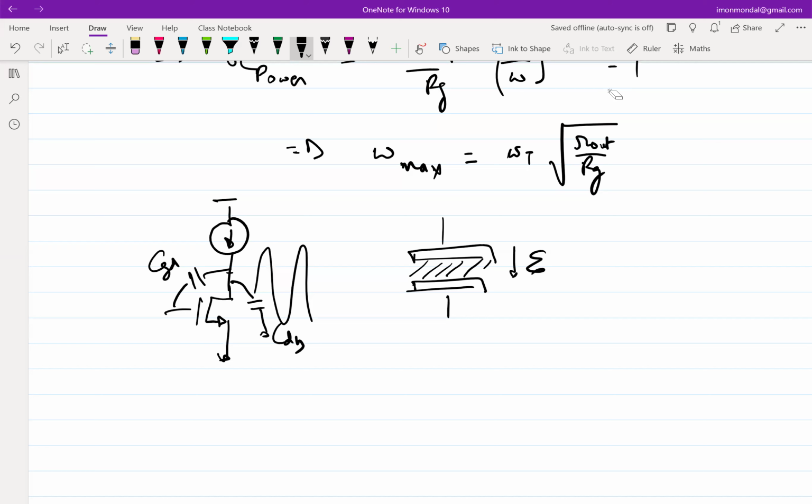Different transistor with a thicker oxide, right? So typically, all technologies tend to have two flavors of transistors at least, one with a thinner oxide, one with a thicker oxide. The thinner oxide transistors will typically be labeled with a lower voltage supply, right? Some NMOS 1 volt, something like that.